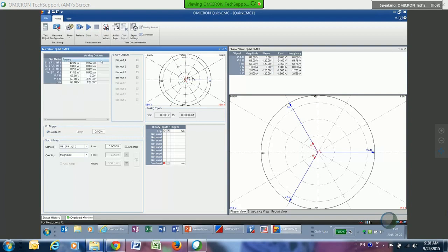And if I want, I could look at symmetrical components, and this is going to show my positive, negative, and zero sequence values for my currents and my voltages. If I want, I could use powers, and it's going to show power values here, watts and VARs, both single phase and three phase. I could do fault values if I want. If I choose, I could do an impedance with current constant, impedance with voltage constant, or an impedance with our source impedance constant. And then you can do percent impedance here if you want.